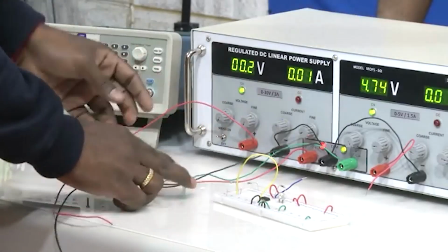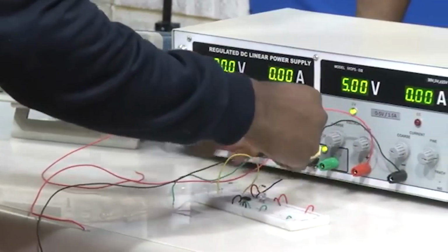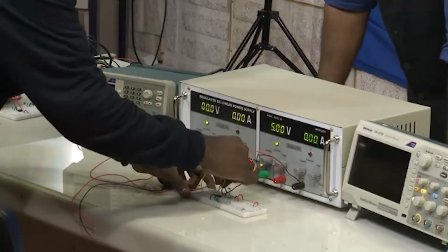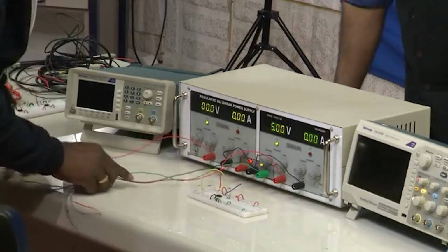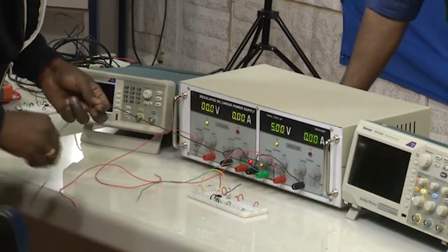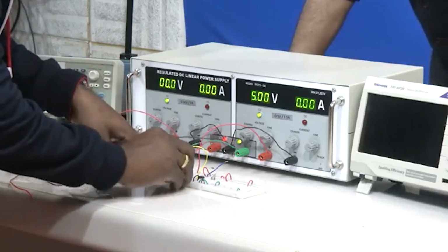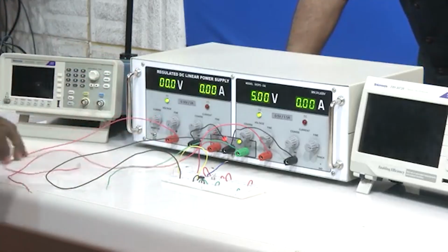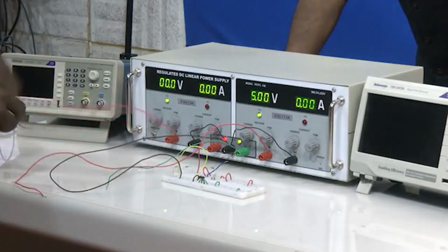We will apply bias voltage across the operational amplifier. So, you all know what is bias voltage, plus 15 minus 15, right. So, for this particular DC power supply, we already know the center terminal, 3 terminals in the center, red, black and green. Through that we can apply plus 15 and minus 15, alright.